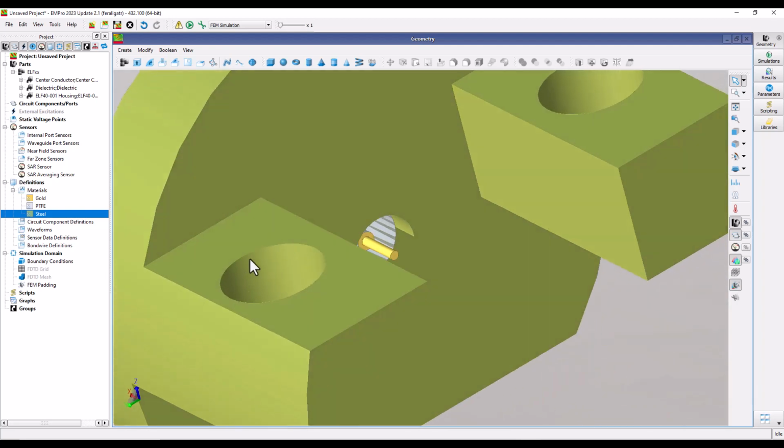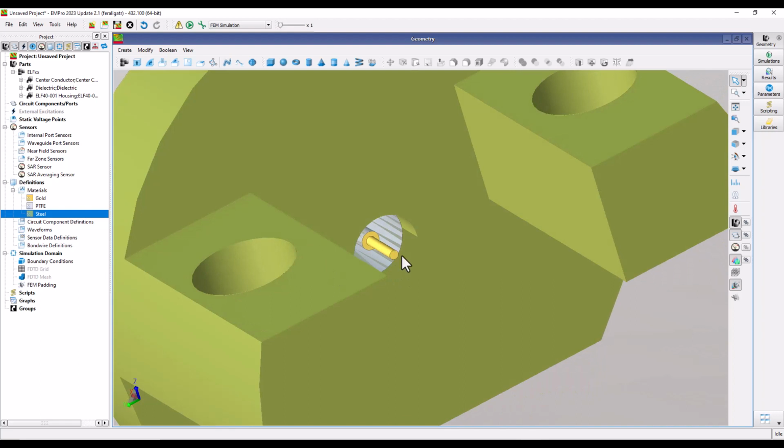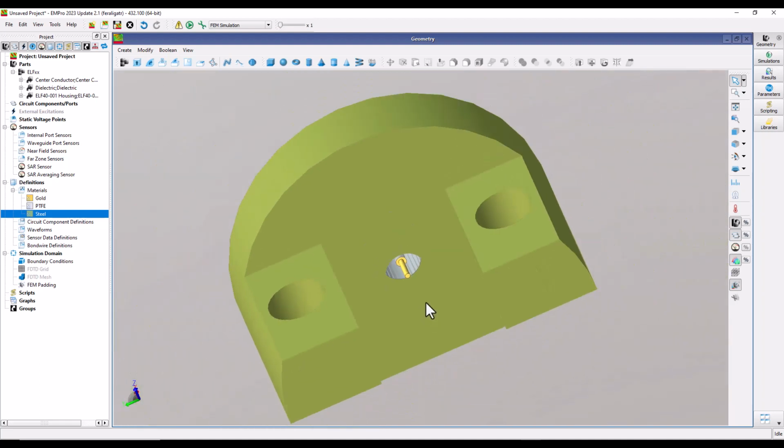But once the energy gets launched from this pin to your board, that is where you need to make sure the transitions happen as smoothly as possible. So even if you don't have this vendor 3D CAD model, I will next tell you how you can model your own, and which is the easiest way. So don't make it too complicated. SMA connector, just a simple coax transition.